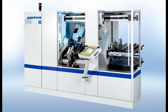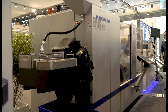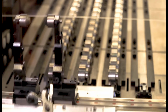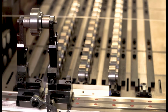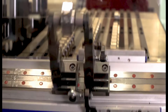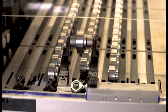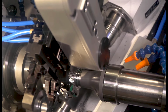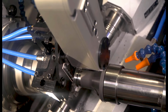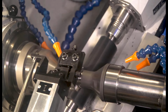This is the Curb 460, a slant bed design machine. It is equipped with automation. It has a gantry loader. Here we see the chute magazine where the workpieces roll down by gravity on multiple rows. And there is the so-called servo distributor that presents the workpieces to the gantry loader. The gantry loader is a high-speed loader with double rotary gripper. And here we see how the workpieces are exchanged in the work area.